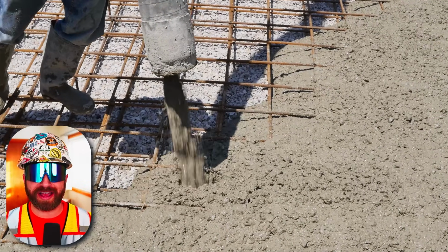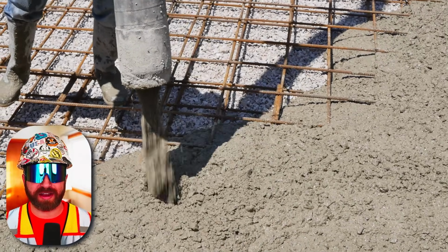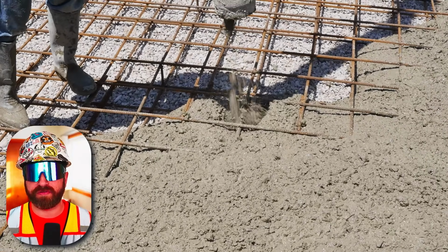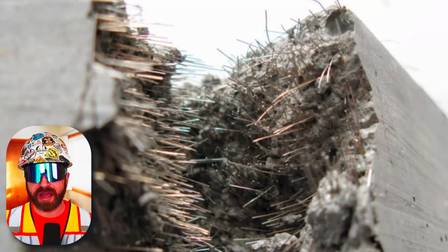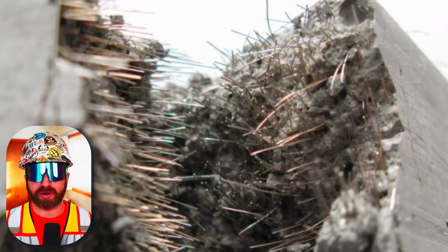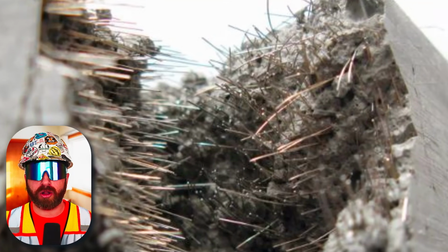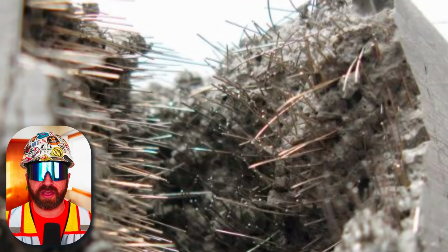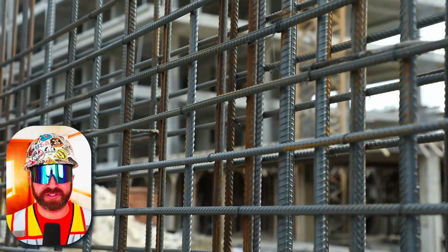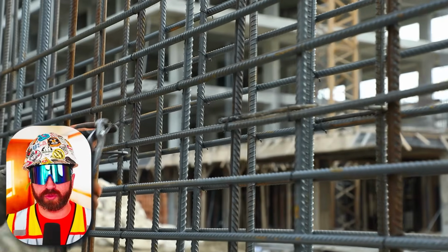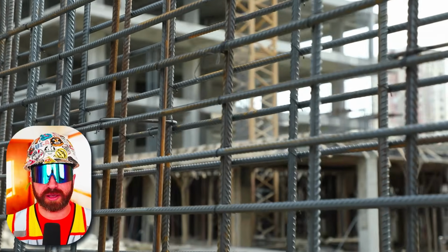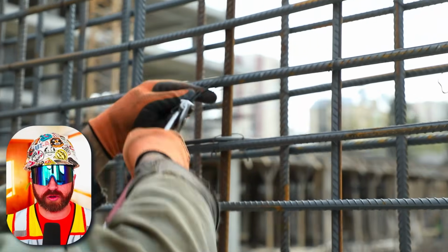Now, when it comes to concrete slabs, there are other forms of reinforcement aside from your typical rebar that could be used instead, such as welded wire fabric or concrete fibers. Fiber reinforced concrete has small strands in the concrete made from steel, glass, or synthetic fibers. The requirements for each project all originate from the structural drawings and specifications in the construction documents. So the rebar gets onto the site, the field installers take those shop drawings and install the rebar according to those drawings. Individuals who bend or tie rebar on site are sometimes referred to as rodbusters and are typically ironworkers.